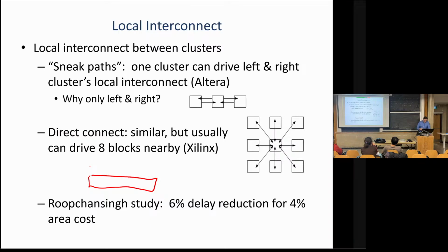And it's actually very tricky to do this because you don't want to sell people a bunch of different chips where you say their timing is different, you need to recompile and so on. Academics have proposed that before, but it's not practical. So FPGAs, people do their design, they validate it, and then they set up basically a manufacturing line to go make a whole bunch of boards that have this FPGA on it over and over again. And there's nobody sitting there running Quartus or Vivado on the production line and madly trying to close timing on every single chip, right? So this would not be good.